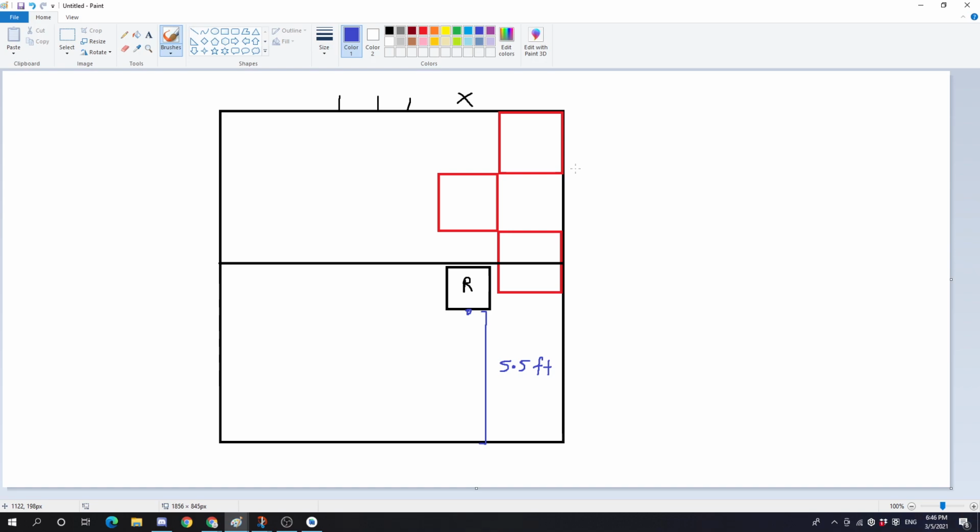For us today, we're going to be assuming that our input is this distance sensor right over here, and this extracts the distance from the back wall. The output is going to be our change in the shooter speed. A lot of teams this year are using a flywheel, and you can adjust the speed using the motor speeds on your flywheel itself, right? Knowing that you have these two options and adjustability, we're going to go ahead and get started with the tutorial.